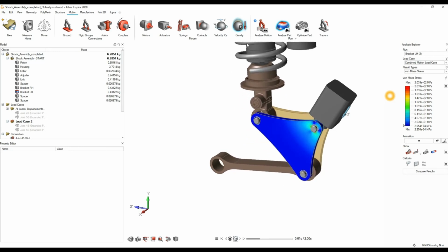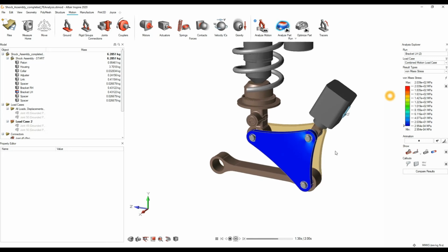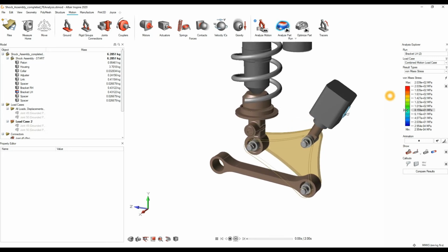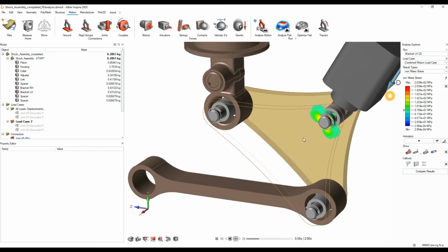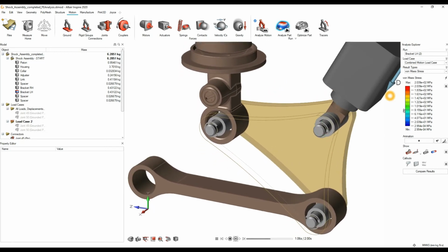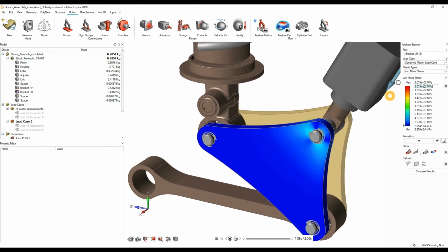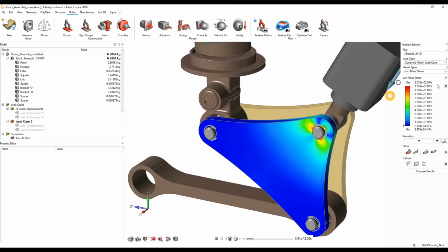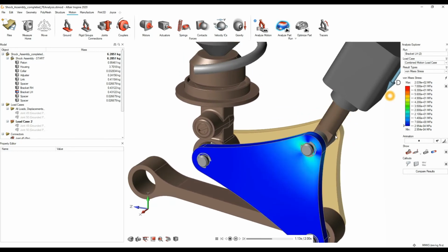But just from that MBD analysis, now you can see exactly what the stresses are that your part will experience. And with this ISO slider here, you can slide it up to a certain value so that it will only show you the moments in the time frame when any of the relevant elements exceed that value of stress. And obviously you can change your maximum and minimum values as well. So if you change that to 100, then you can see more areas that are affected.